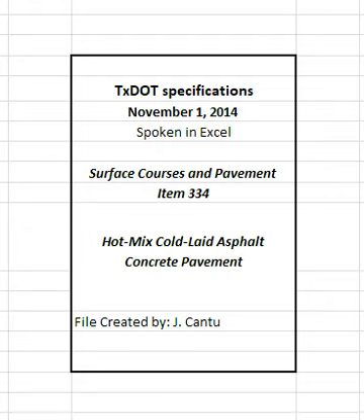Defer compaction after placing the paving mixture, as directed, to allow for volatilization. Allow the previous course to dry and cure before placing the next course when placing more than one pavement course. Consider the course cured if the hydrocarbon volatile content of the mixture is 0.4% or less by weight of the mixture when tested according to TxDOT 213F unless otherwise directed.